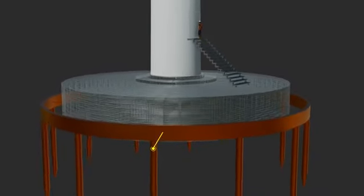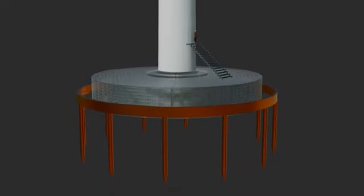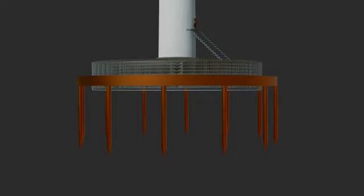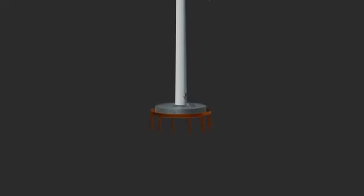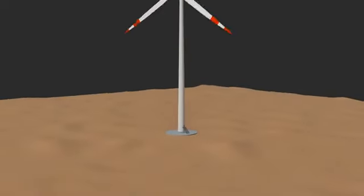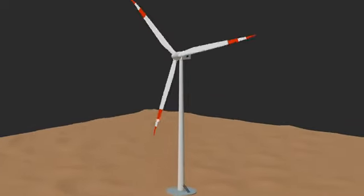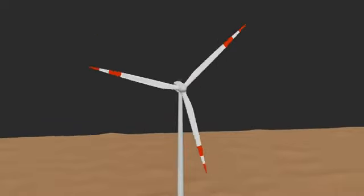Multiple vertical ground rods are connected to the ring electrode. These rods, typically 2 to 4 meters long, are driven deep into the ground to reach lower soil layers with better conductivity, enhancing the grounding system's effectiveness. This comprehensive grounding system ensures that lightning strikes and electrical faults are safely dissipated into the earth, protecting personnel, equipment, and structural integrity. These remarkable machines represent decades of engineering innovation, delivering sustainable power to thousands of homes while operating reliably for 20 to 25 years in challenging environmental conditions.